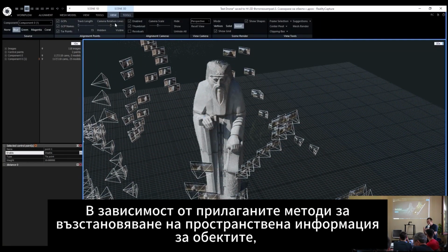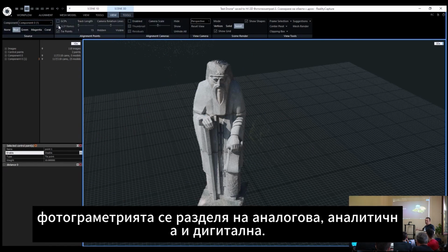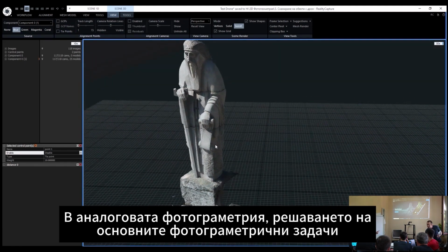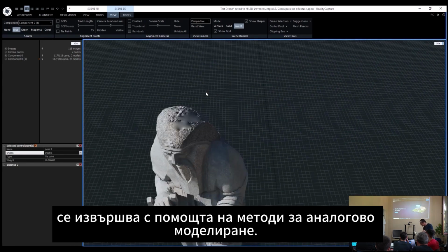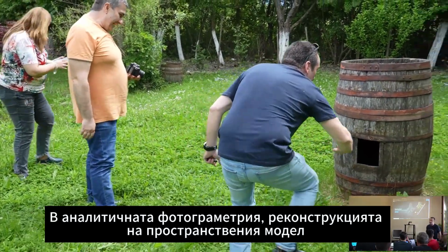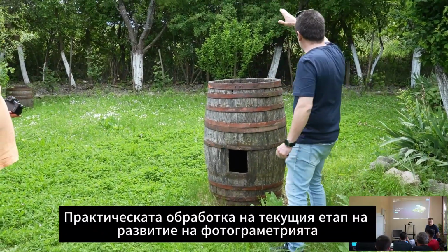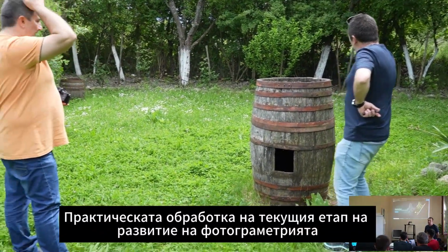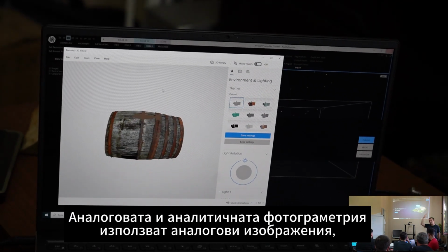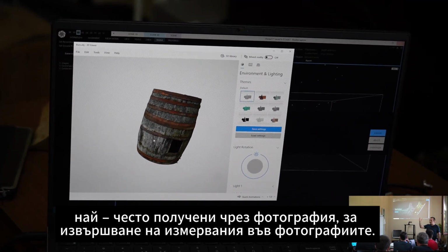Depending on the applied methods for restoration of the spatial information about the objects, photogrammetry is divided into analog, analytical and digital. In analog photogrammetry, the solution of basic photogrammetric problems is performed using the methods of analog modeling. In analytical photogrammetry, the reconstruction of the spatial model is done by computational means. The practical processing at the current stage of development of photogrammetry is done on a computer. Analog and analytical photogrammetry use analog images, most often obtained by photography, to perform measurements in photographs.